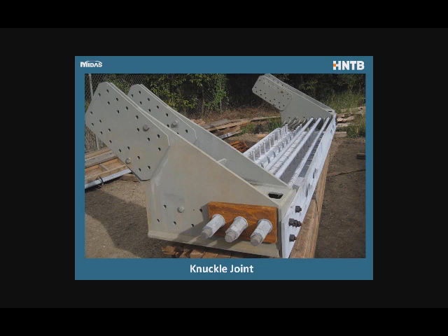But then you have to transmit the thrust that's coming down from the arches, and you have to get that over to the tie girder, to the post-tensioning tendons, and that's what that shear stud plate accomplishes. The bars with the nuts, they're actually there for bearing replacement. When you have bearing replacements, we place jacks just inboard of the arch rib, and that creates a huge moment gradient, and the nuts are needed to develop the rebar more quickly through that knuckle joint here.